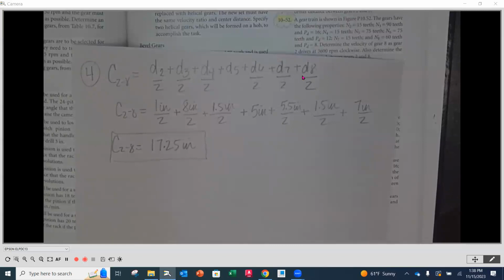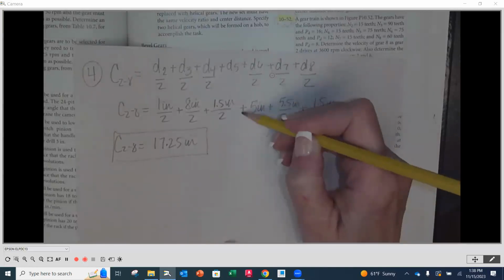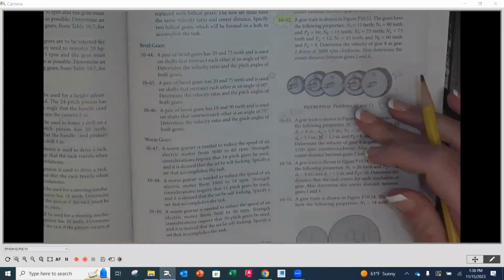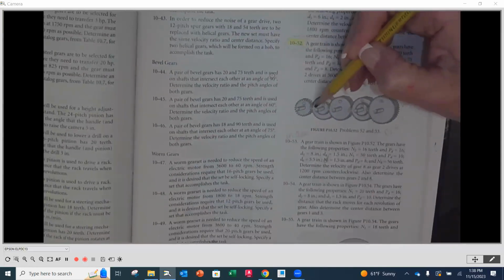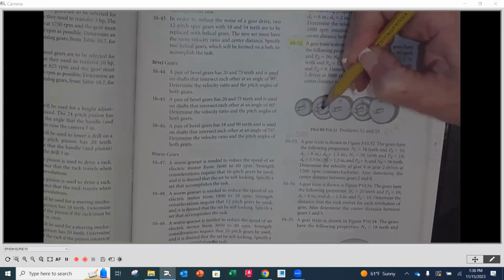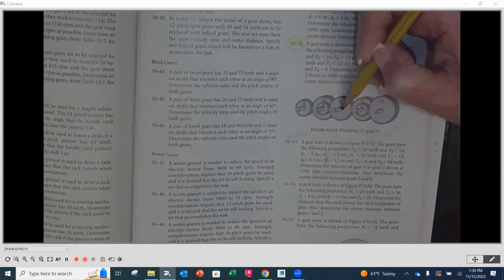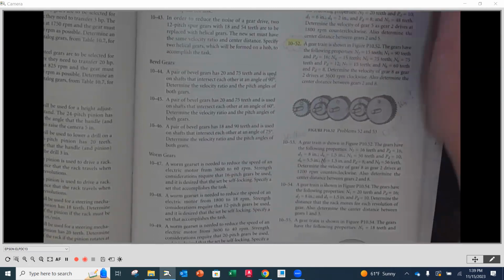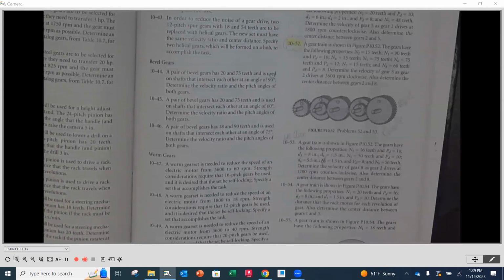Good. If you got it right away, that means that you remembered the idler. Okay. You remember the idler, and the way that it's positioned here, we have to take the diameter because it's an engagement on one side and the other. So if we look here at what's going on, we go from the center line of 4, that's the radius of 4, but then we go to the center line of 5, and then back to the center line to 6. So we take the entire distance across of 5, okay? So it has to be the full diameter of 5. That's the only one. Otherwise, the rest of them are their radiuses.